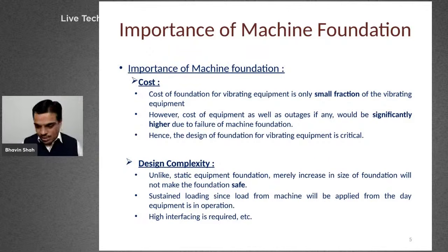By increasing the size, our foundation may become safe or it may become unsafe, because by increasing the size of the foundation, we may get closer to the operating frequency of the machine. Because of that, the amplitude could increase beyond the permissible limits and it may become unsafe. So this is the major design complexity involved in the machine foundation. Merely by increasing the size of the foundation, we cannot say that it is safe.